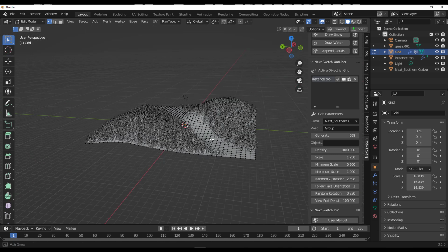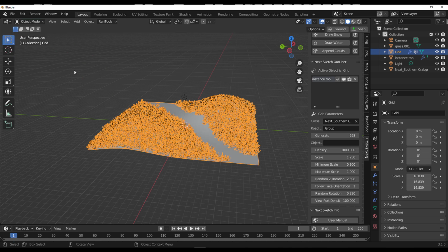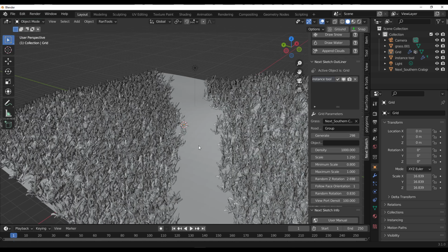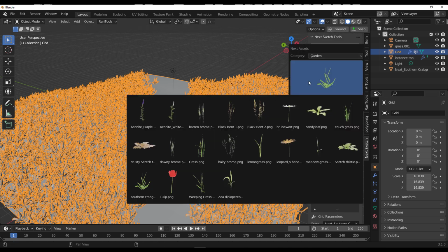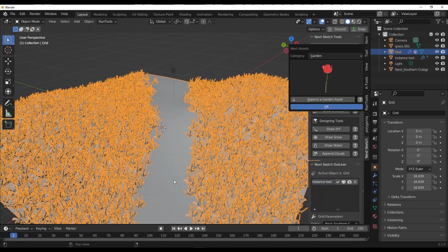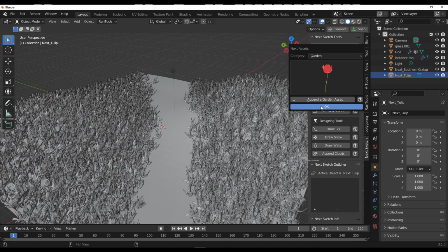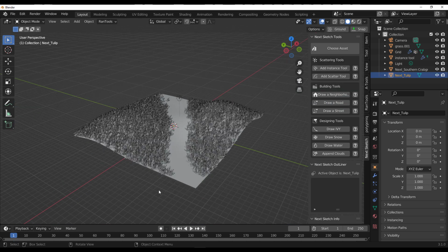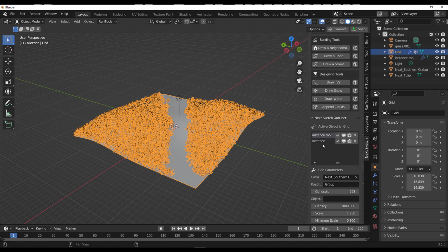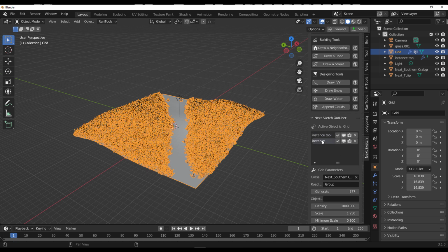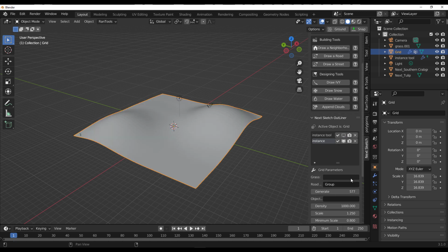And to append multiple stuff here is also very easy. So in this case, what we would like to do is have the surface selected, go all the way up, and we would get the tulip. So let's try out with the tulip. Click on append, click on OK, have that there, have the surface selected, and then click on the instancing tool one more time. And since we're dealing with a second instancing tool, I'm just going to turn this off so that we can append that tulip.